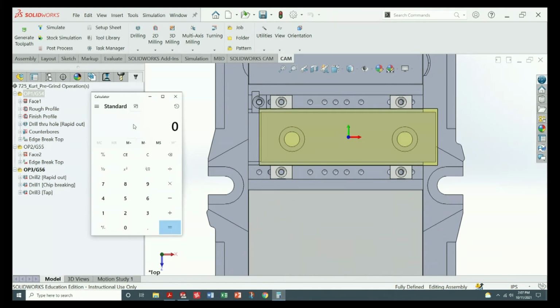RPM you already know how to do. We came up, I put 1100 for my RPM because I didn't want to mess with the 1146. So I know the RPM. How many flutes are on my cutter? 4. I'm already there. 1100 times 4. Just gonna hit enter and hold that there. So there's 2 of the parts of my equation, and those are given.